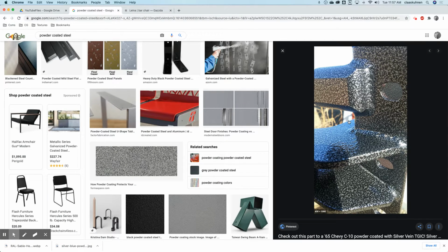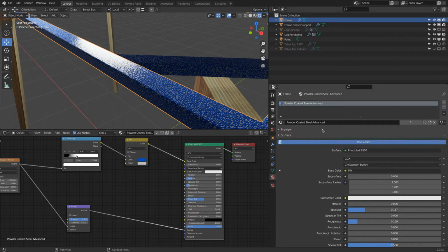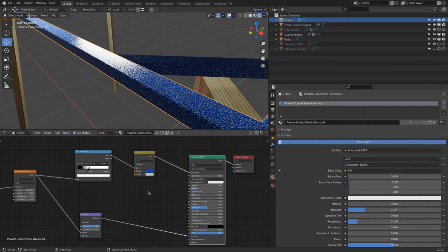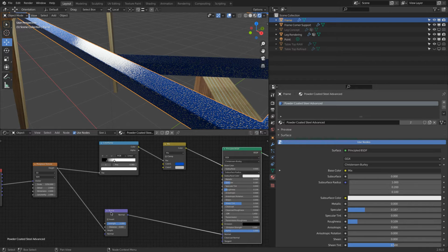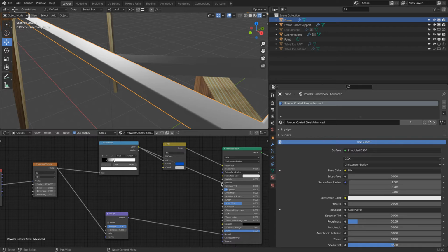Here in this, we can see how everything is kind of reflective, but maybe we would like only to have reflection on top of these corners. The inner parts maybe are less reflective, just to show you how we can achieve something like this. So we have here our bump mapping. We have this, and this, for example, I will put into the specular channel.